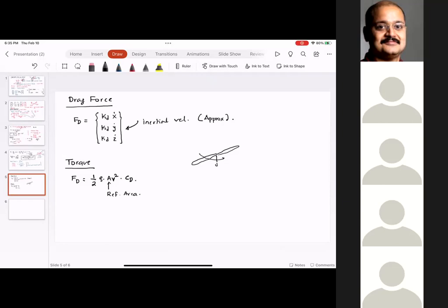So the drag torque is equal to 1/2 multiplied by the radius multiplied by the force, which is rho Cd A v square, and v is the pitch line velocity of the prop. This is the velocity which is dependent on angular speed.